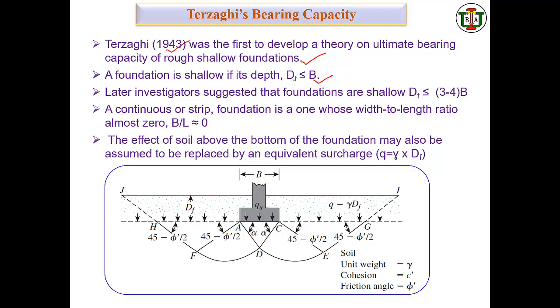If the width of the foundation is higher than or equal to your depth, that time you call it shallow foundations. Or in other words, if the depth is less than or equal to the width of your foundations.